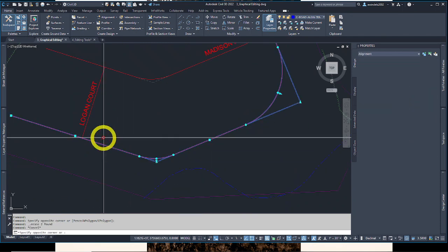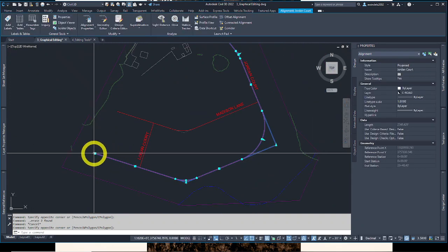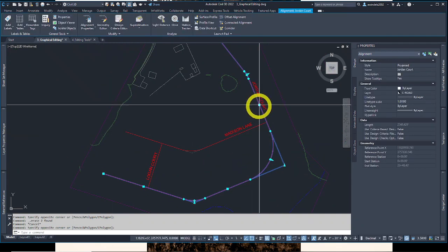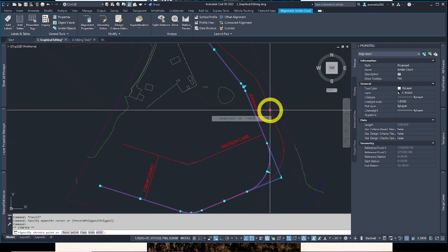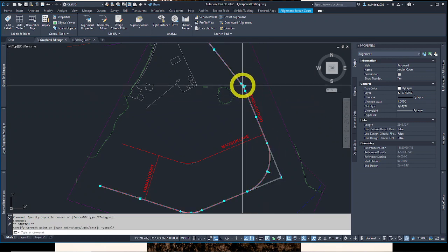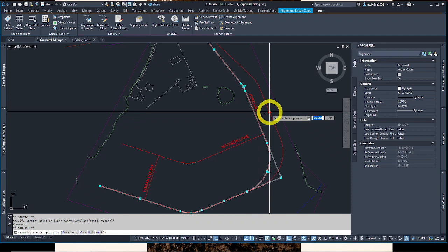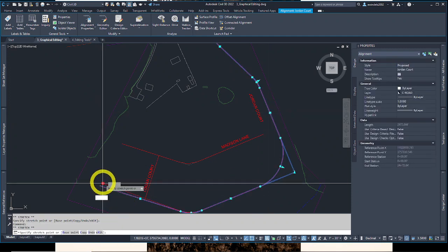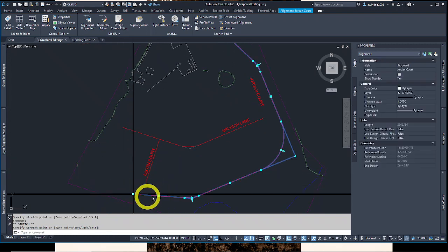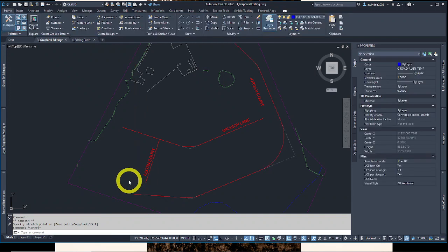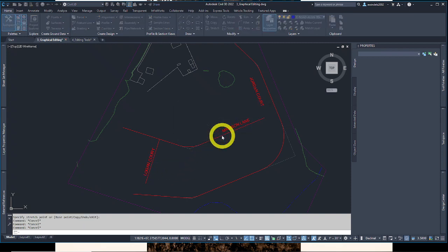And the last one it's talking about is you can grab the tangents, the squares, and just the tangent ends, or this one here. It moves everything associated with it to remain tangent, the tangency on the curve to the north and the south. So this curve and this curve, as you move it, it maintains those. This one does it a little differently since you have a free end. It maintains them as well, but it creates a different tangent location in the XY. So it's just showing you can do that as well. That's it on 5.3. We're going to move to the next file, editing tools. Close this. I'll just hit yes to save that for next time.